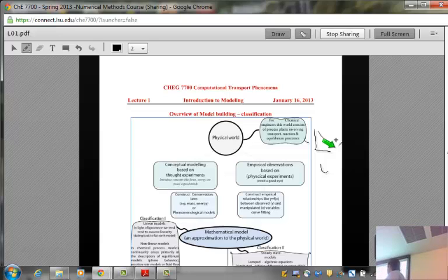So you can pose a lot of these questions. That's another approach, thought experiments, conceptual, and those are much more widely applicable. Whereas these experimentally based ones are applicable only for a close class of experiments. But we need to put these together. So construct mass and energy balance equations, construct phenomenological and empirical models, PV equals nRT, etc., and put them all together to get a mathematical model, which is a comprehensive model.